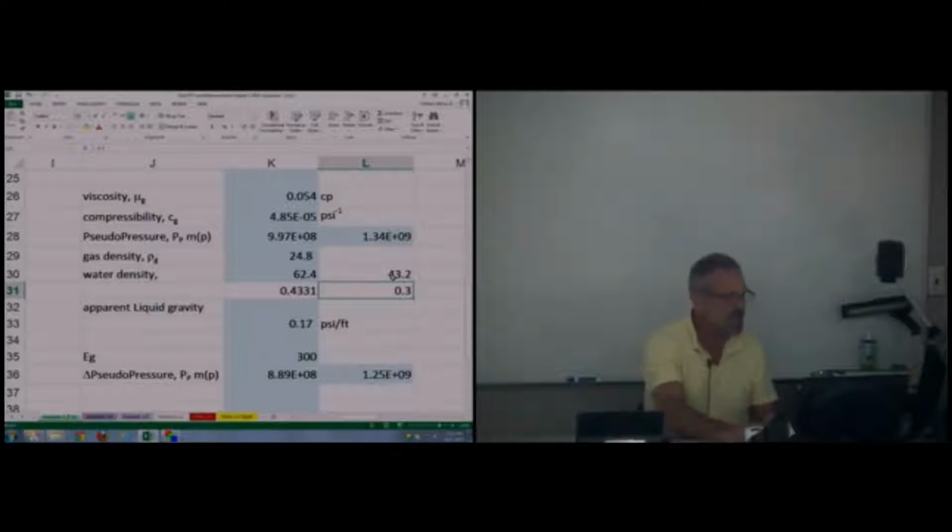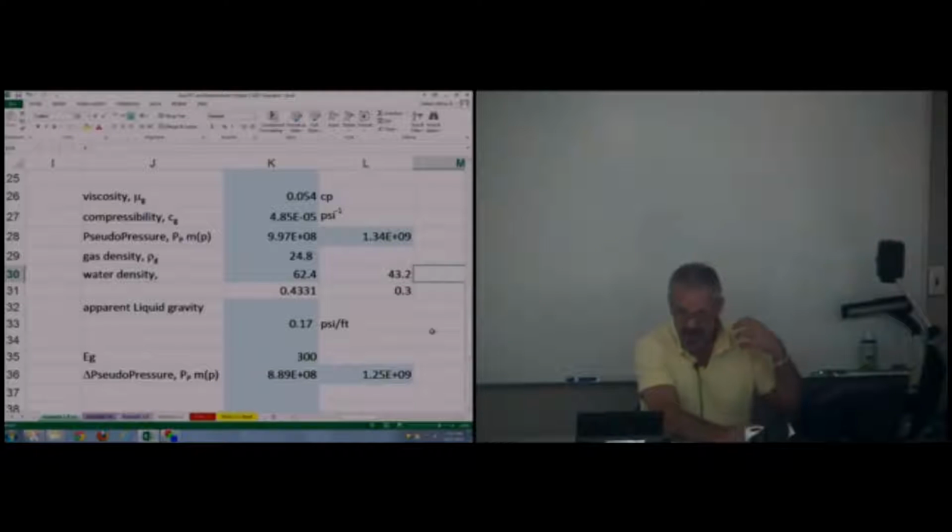Now you could also say that it's, let's say it's an oil. We know it's an oil. We can't say what its specific gravity is compared to liquid, because in order to convert that to API, we would have to know its specific gravity at atmospheric conditions. We just know its density at temperature and pressure.